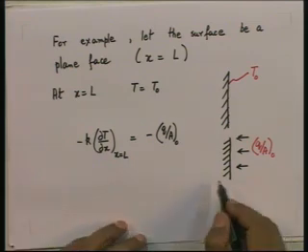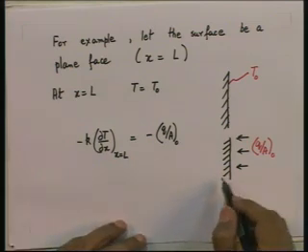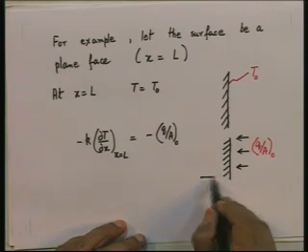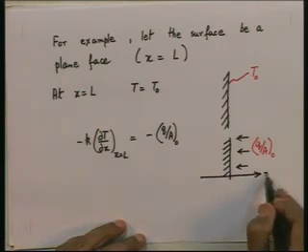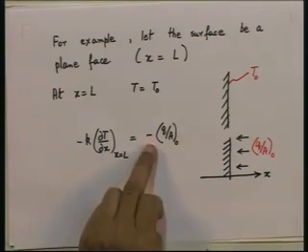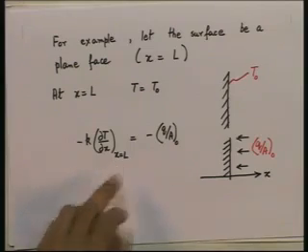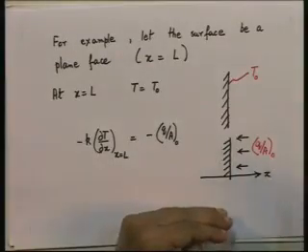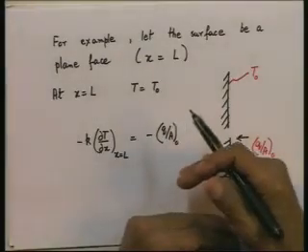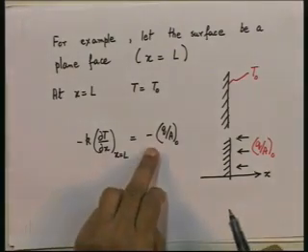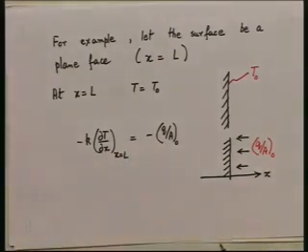And mind you, I am calling this the positive x direction. That is why I put a minus sign on the Q by A here. Minus K dT/dx at x equal to L is the heat flux by conduction in the positive x direction. This has to be equal to the Q by A falling, which is shown falling in the other direction, therefore it is equal to minus Q by A naught. So, this is the second type of boundary condition.